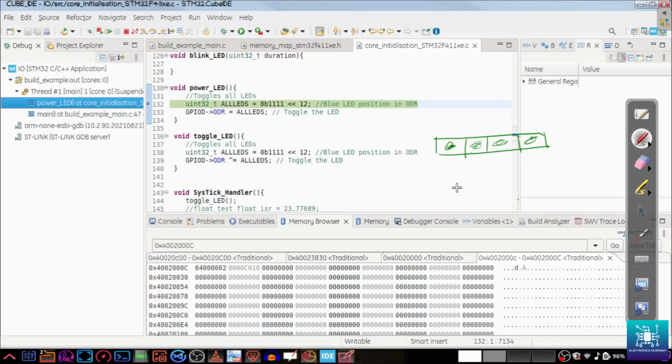Even this configuration was done in the GPIO. Now in the GPIO output register, if you feed a 1 to all these bit positions all together, only the port that is designated as the output port will let the signal out and glow the LED. It will power on the LED.